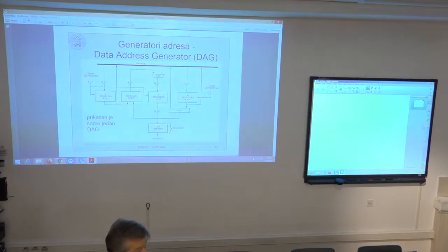That is useful if, for example, in your application you need only a given number of modifications: update by +1 or by +2, or update by -1, so increment by 2 or decrement by 1. Then you can preload these values in these 4 registers, and simply invoke one of those registers as a modification register after the fetch instruction.